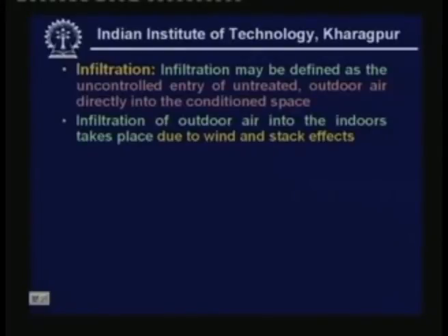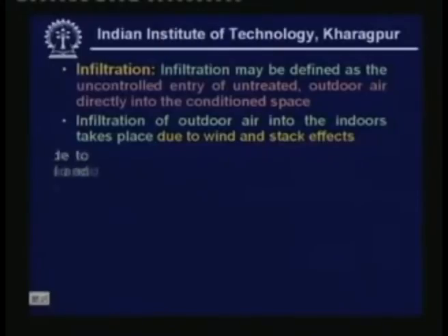This is nothing but the entry of outdoor air because of the buoyancy effect. The buoyancy effect is created because of the temperature difference between the inside and outside. Whether it is summer or winter, the inside temperature will be different from the outside temperature. Because of this temperature difference, there will be density differences between the outside air and inside air. And if your building has some openings, because of the density differences, there will be entry of outdoor air into the building and the same amount of air leaves the building. This is what is known as the stack effect.